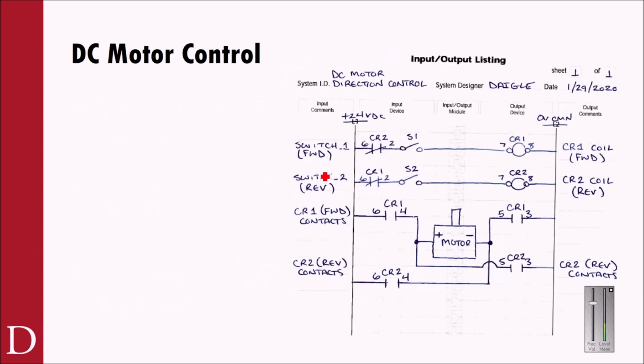DC motor control. So we talked a little bit about DC motor control, but the ability maybe to trace the circuit here. First of all, what we have down here, if everybody remembers, we call this an H bridge. The reason why is it looks like the letter H. You can kind of see it here. I've got the 2 sides here and here, and I've got the middle that makes up the H. This is essentially the circuit that you guys used on the elevator control circuit.